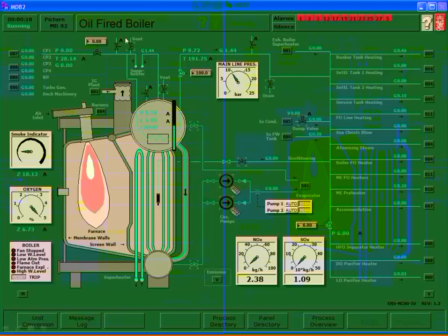Superheater vent, for this scenario, we're going to leave it open all the time. And again, think about, I want steam flow, so I'm going to leave the superheater vent open, and I'm going to want to leave the desuperheated steam stop open. And here is my drain for the services, and I would leave that open until all the water had been removed and I was getting steam output. Again, as soon as this boiler starts producing steam, I want flow through the system to protect the superheater.